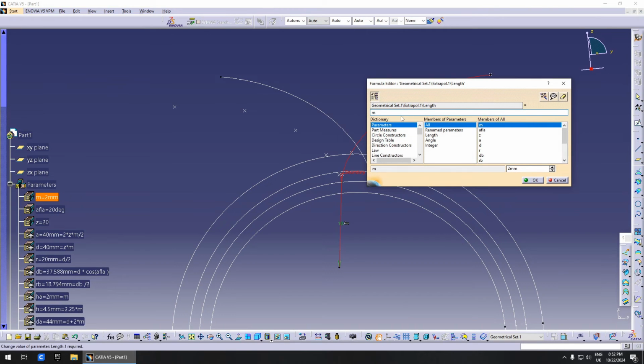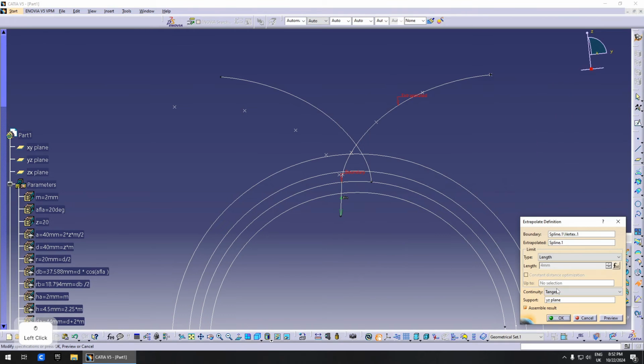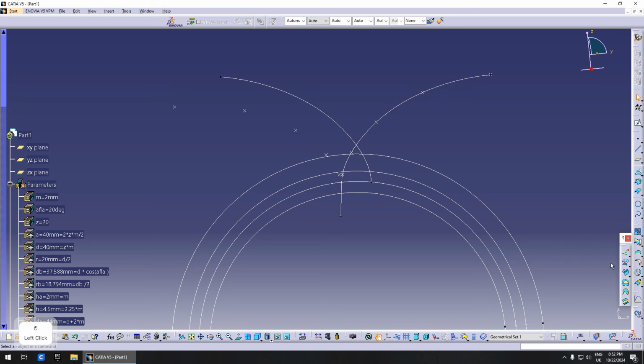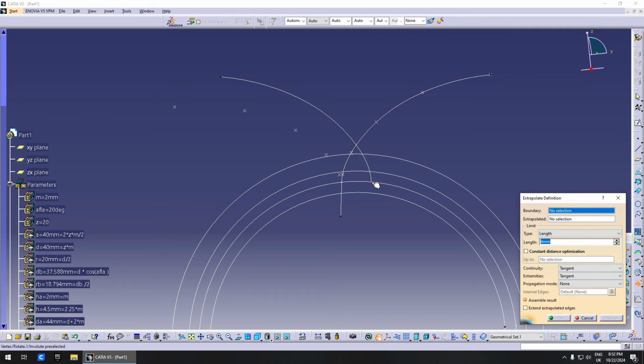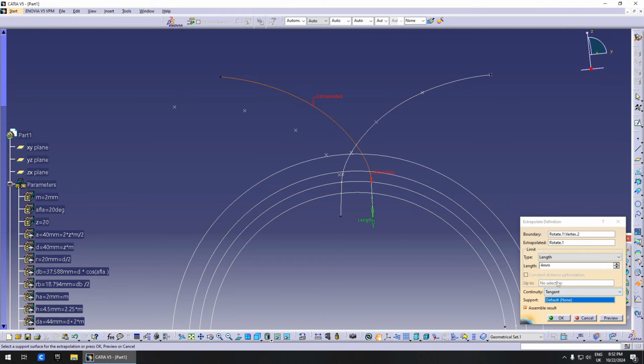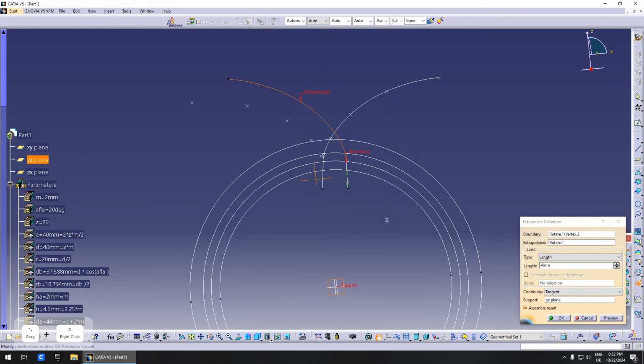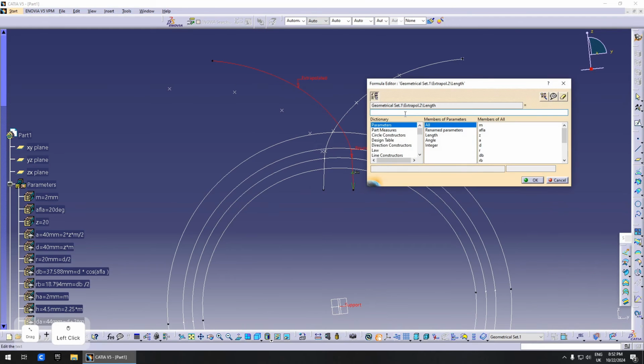Module 2 millimeters, that's kind of not enough, so 2 times the module, something like that. We can have this like that as well. It's always good to have a support if you can, and we link it to the module like this.